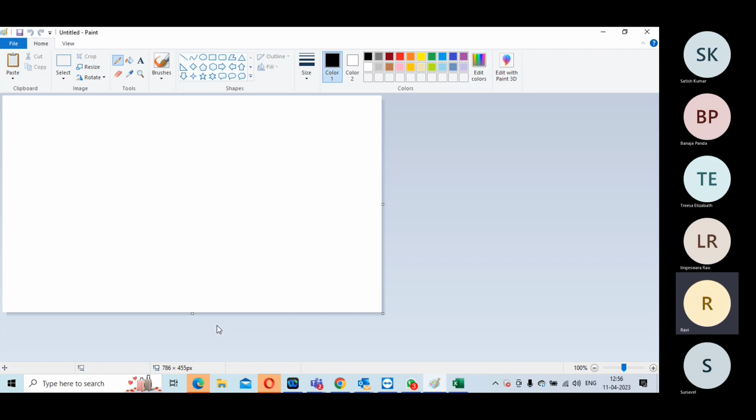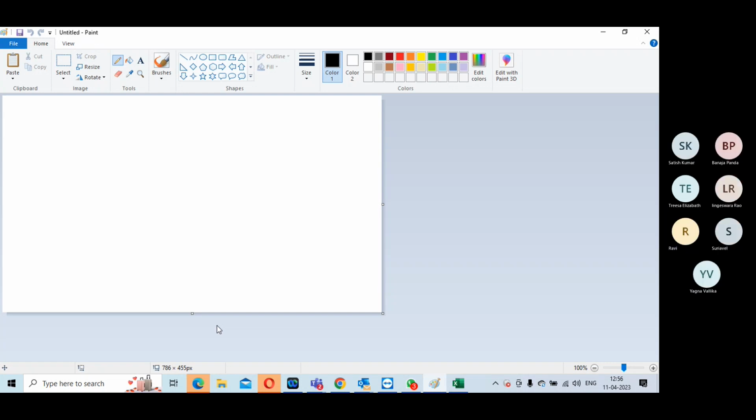To meet 2 gigahertz, you have only 500 picosecond available to you. How many buffers can you add? 50 picosecond is one buffer delay, so not more than 10 buffers. 10 into 200 is 2000 micron is what you can drive. That means you need repeaters. If you have 8 mm, you need at least 4 repeaters, 4 flops in between to meet that frequency. 4 repeaters per net multiplied by 2,600 becomes 10,400 repeaters. Simple. These are all mathematical calculations you have to do.